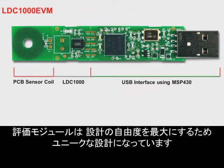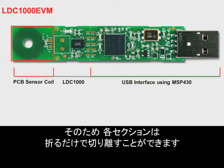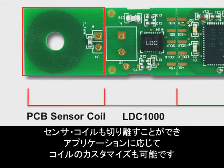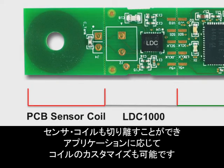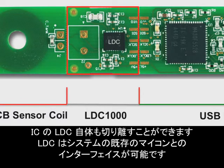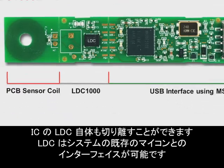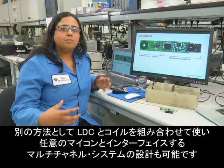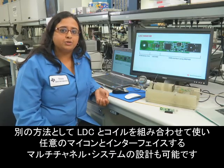This EVM is uniquely designed to give you as much flexibility in your design as possible. So each section can be separated by just snapping a portion off. The sensor coil can be snapped off, and you can use your own customized coil for your specific application. The LDC IC itself can be snapped off, and you can interface the LDC to an existing microcontroller in your system. Alternatively, you could also use combinations of the LDC and coil to design a multi-channel system interfacing to your microcontroller.